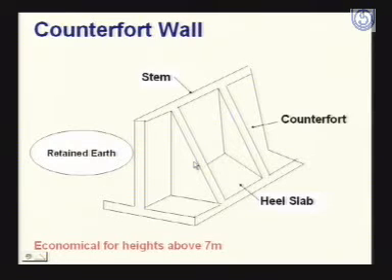Here these counterforts subdivide the vertical slab into rectangular panels and support them on two sides in a suspender style, and the counterforts themselves behave as vertical cantilever beams of T section and of varying depth. As you can see, the depth is maximum here and minimum here. So these act as a T-beam of varying depth.